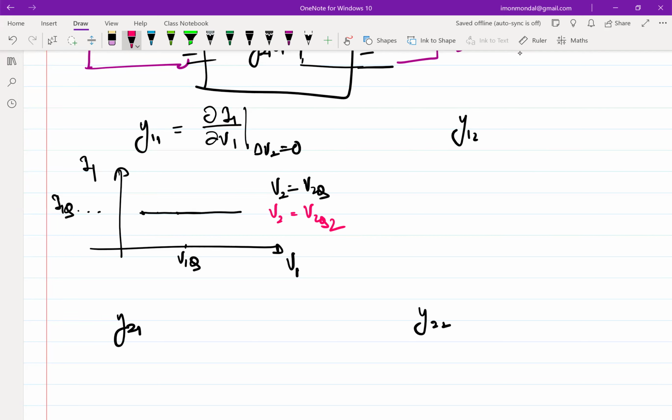Okay, so I changed the output quiescent voltage, and I would like to draw the same plot. Again, do you expect the new I1 versus V1 plot to overlap? Is it necessary that it overlaps? No, right? It can be another plot, but as long as it is flat, I am good, right? So it can be something like this. That's all right. This is something that we want. This is expected. Okay.